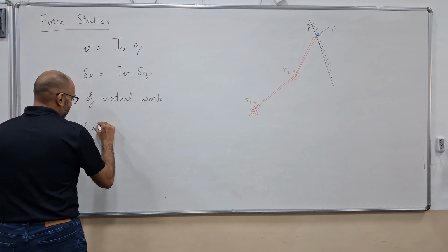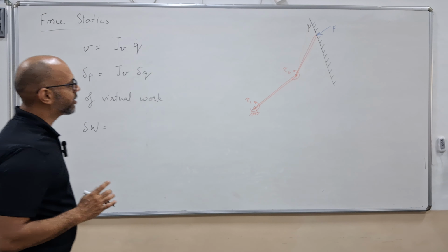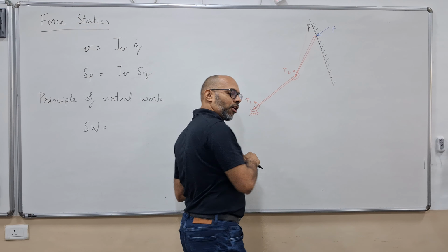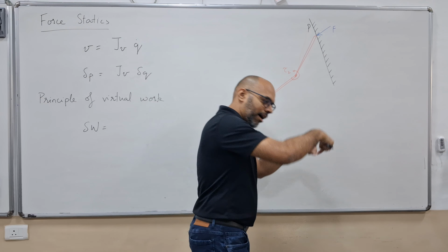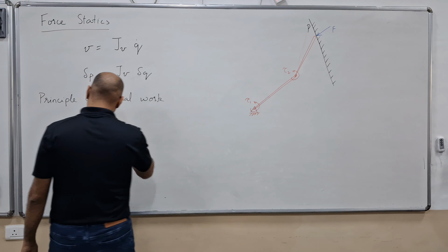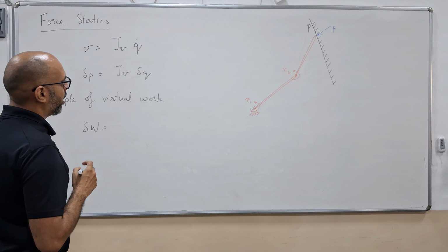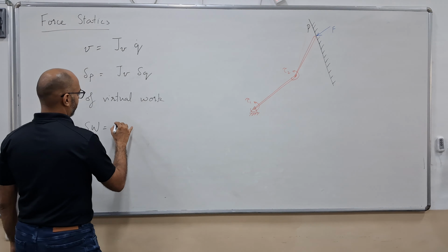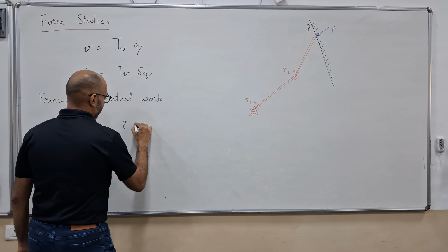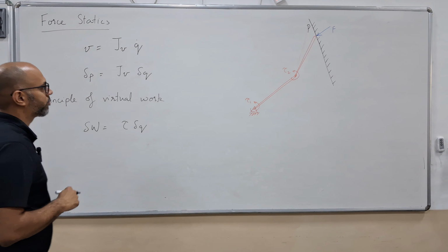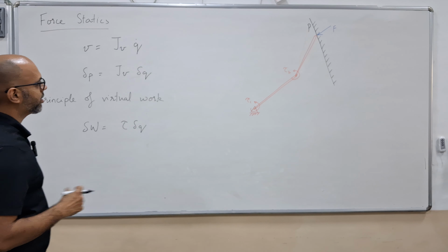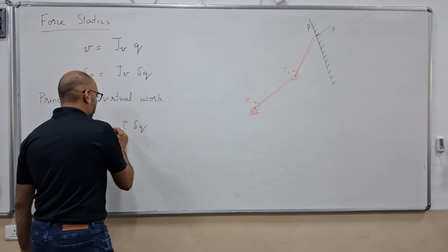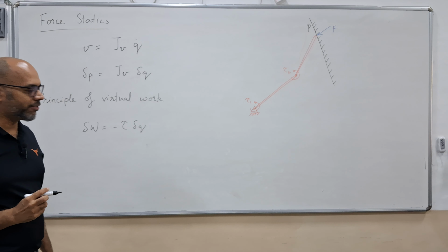Basically, in our case, the virtual work will consist of two things. One, there are external torques being applied on the robot because a motor is applying a torque on the robot, right? So you would have a work done due to the torques. So you have a torque times delta q, and since this is work done externally, work done on the robot, I would treat this as a negative work.